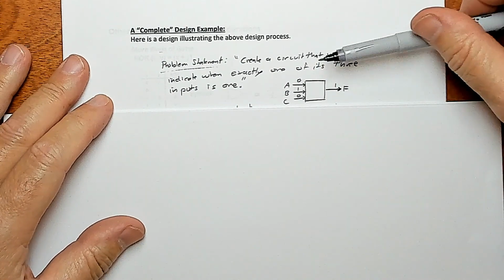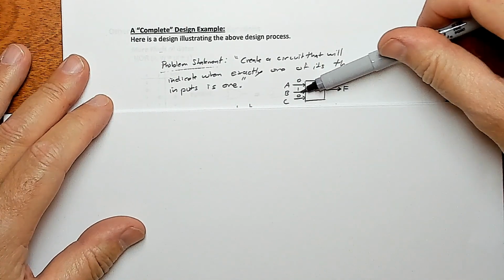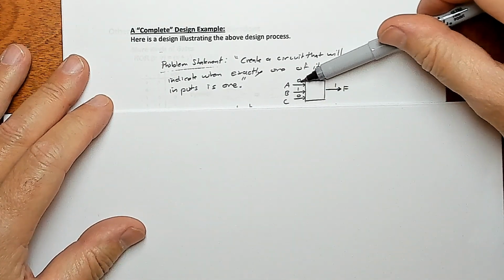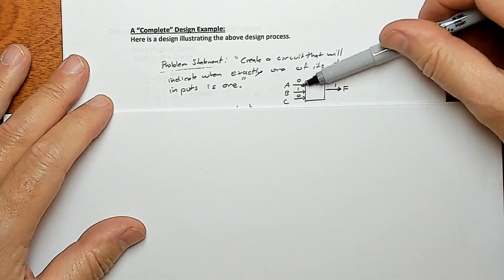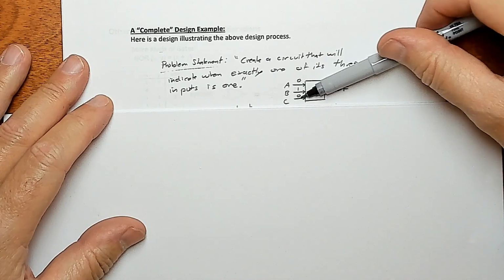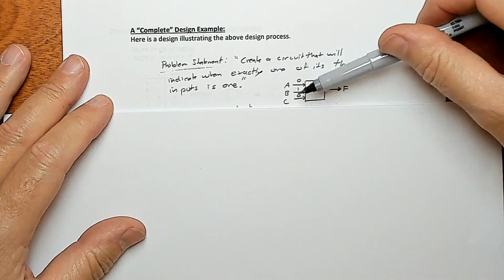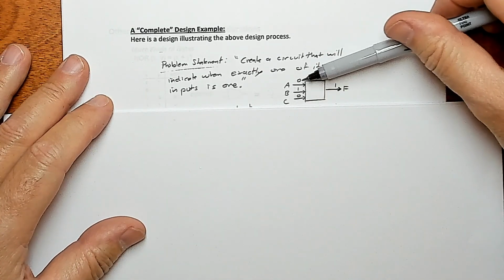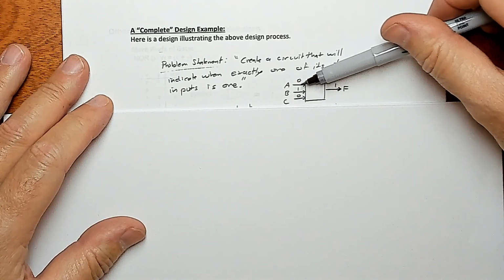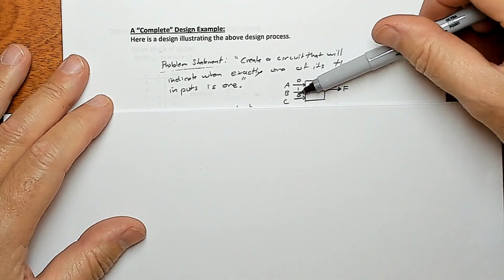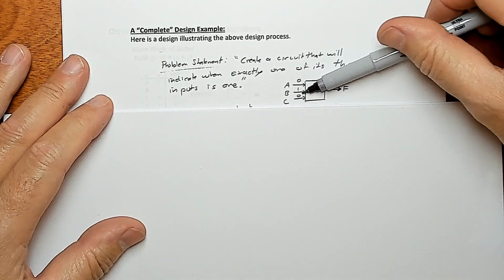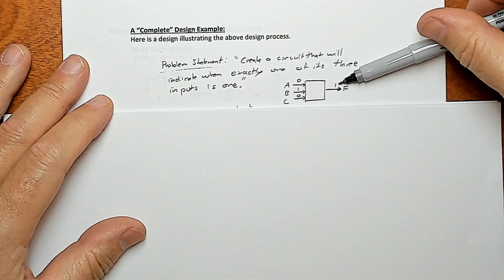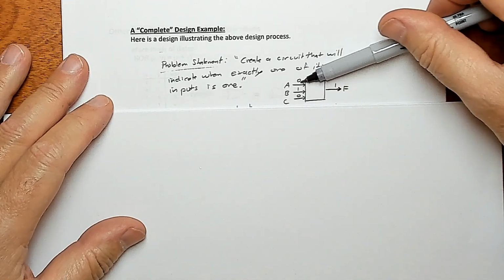For some reason you need this, all right? So we've got 3 inputs, and they can be 0s or 1s, and there are basically 8 combinations of inputs that can go in here, from 0, 0, 0 to 1, 1, 1. In this case, we want F to light up because exactly one of these 3 wires is 1.